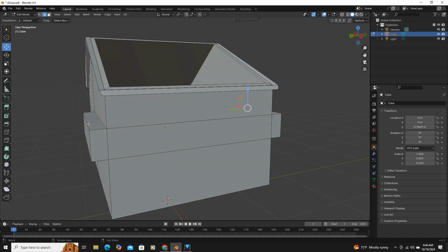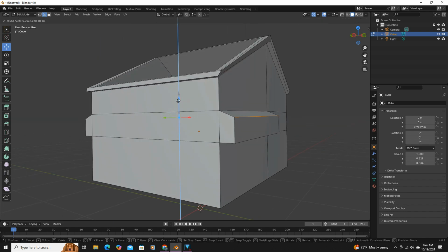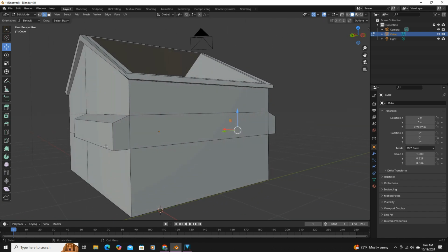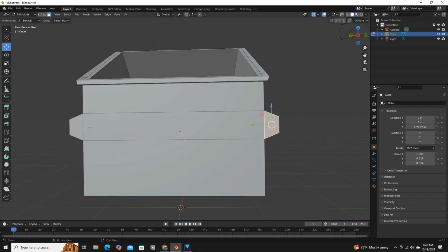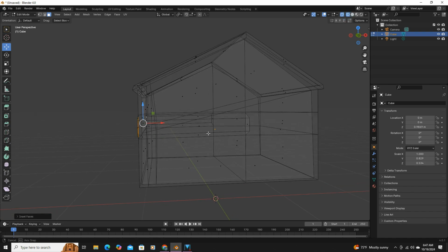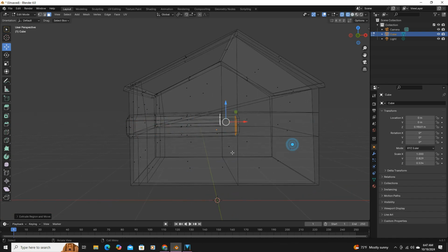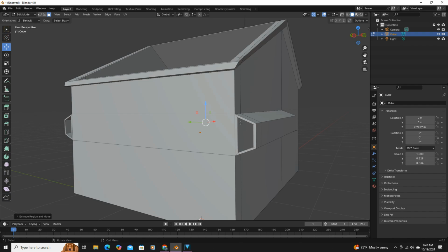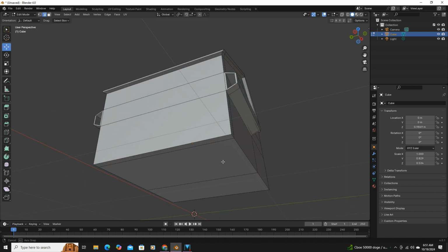Select the top outer edge of each sleeve and use the Gizmo tool to move them slightly downward. Do the same for the bottom edges, moving them slightly upward. Select both faces at the front of the fork sleeves, press I to inset, switch to wireframe mode, and press E to extrude, recessing the faces all the way to the back.